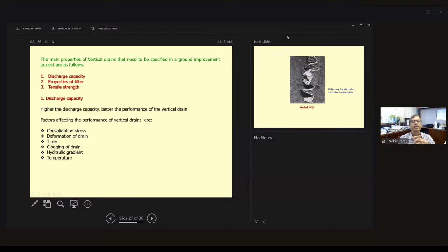When you talk about the filter, we need to know that it is a geosynthetic material, right? I hope everyone knows that there are two different types of geosynthetic material. We will talk more about that. In this case, you need to check the opening aperture, and based on that there are different soil retention criteria. We need to check the D85 of the soil, and O is basically the property of the geosynthetic material.